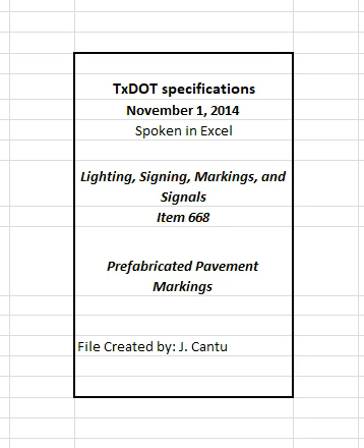Furnish prefabricated pavement marking materials used for contrast markings in accordance with DMS 8240, permanent prefabricated pavement markings, with the exception that the color requirement for the black contrast portion does not have to meet the color requirements specified for white or yellow markings. Store all materials in a weatherproof enclosure and prevent damage during storage.